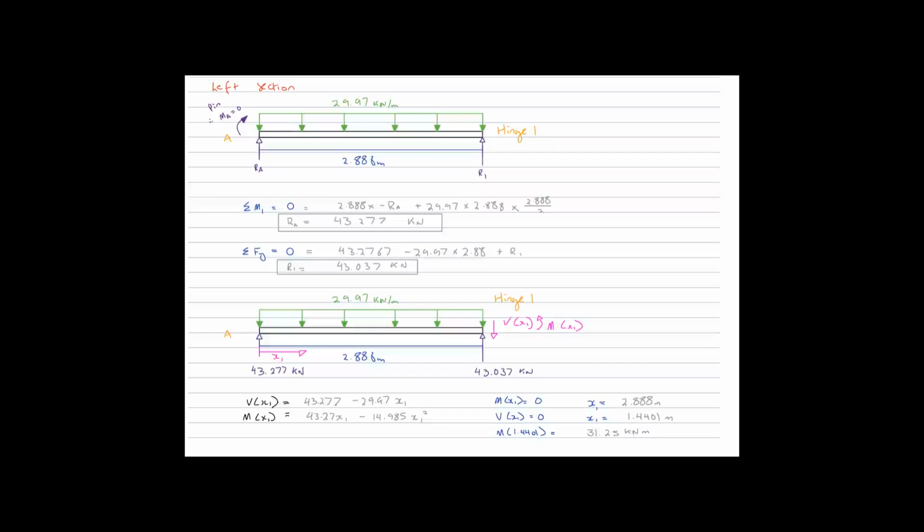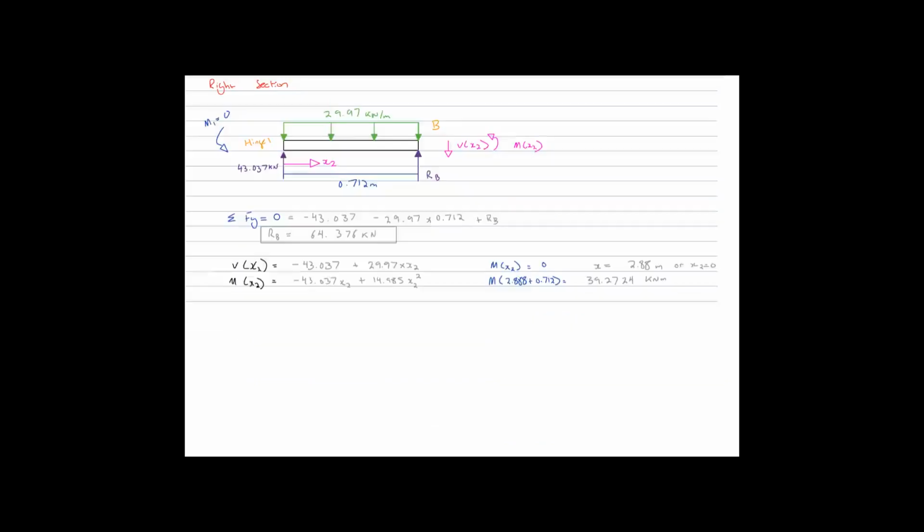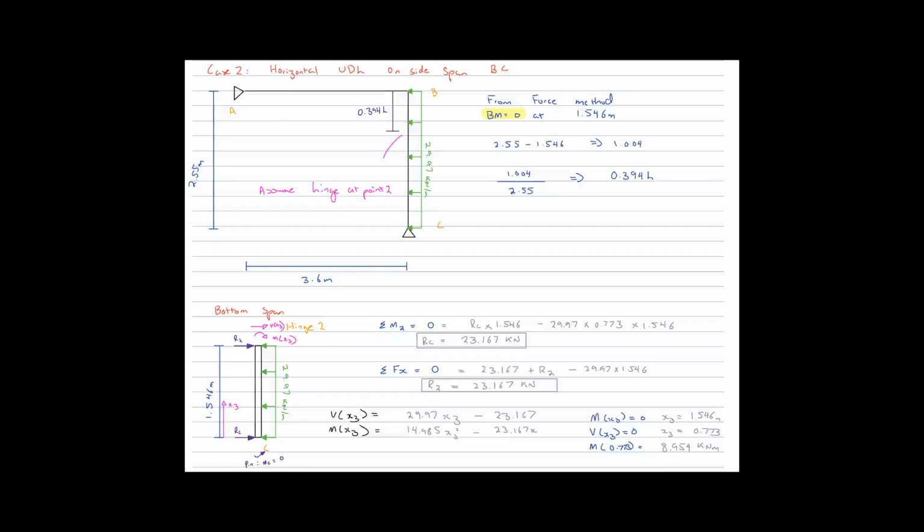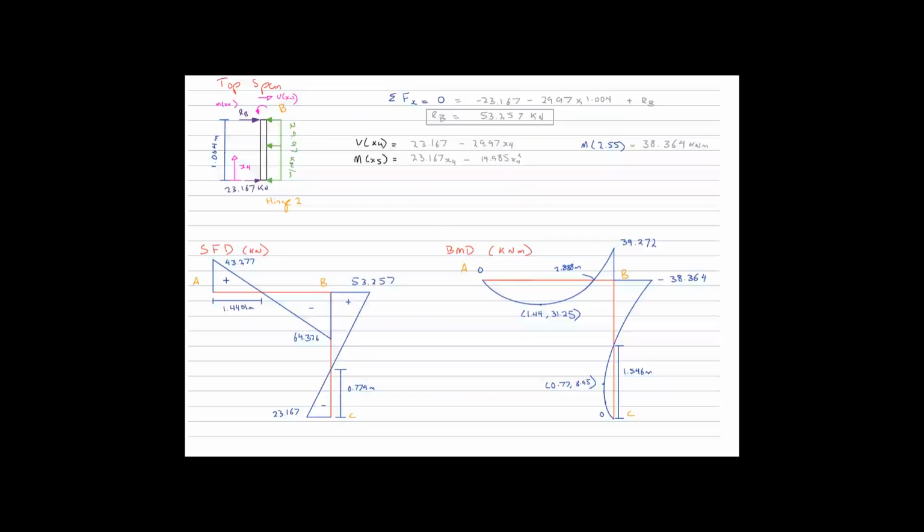This method takes a more simplistic approach, where I take into consideration 2 load cases, the top or the side load individually. Then in each case, we analyze each the beam or column on the left or right or the top and bottom sides of the hinge. In these computations, we first calculate the reaction forces and then solve for the internal forces, allowing us to calculate moments.